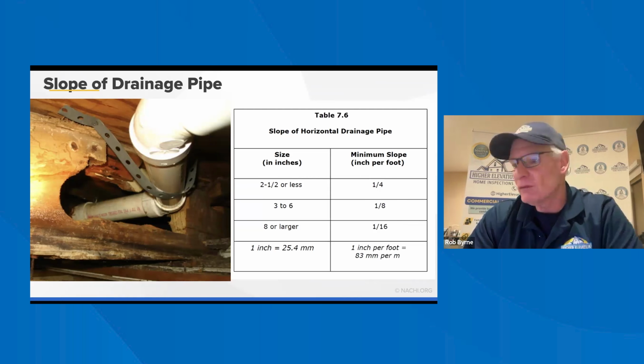And that's the type of thing you look at visually. If you see the sewer lines inside the basement, and sometimes you see that the slope is too much, what happens is the solids stay behind. So that's important to understand and comment on. If it's not sloped enough or too much, you kind of get an idea.